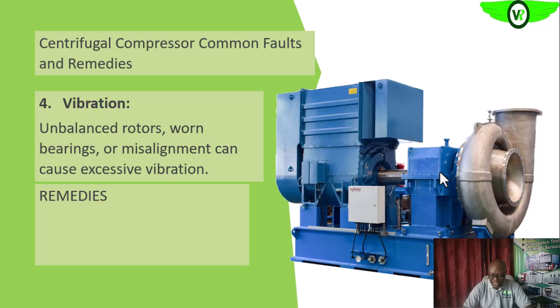So what are the remedies? If we notice that we are having high vibration, we can carry out vibration analysis on the motor, on the gearbox, and on the compressor end. Okay, so that analysis will tell us what is happening. If we are having unbalanced forces, they will show.